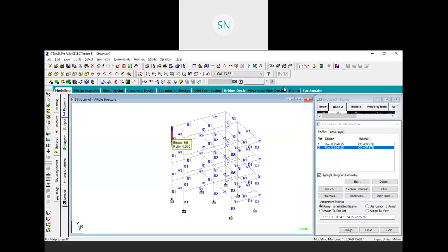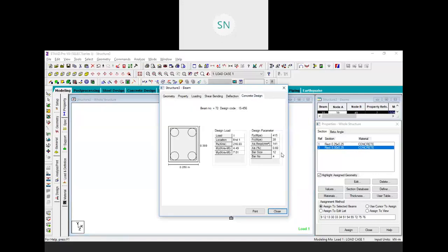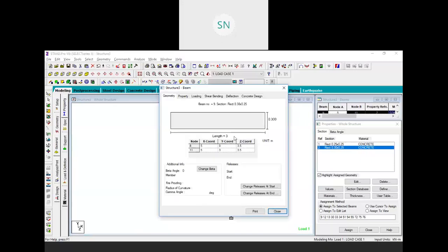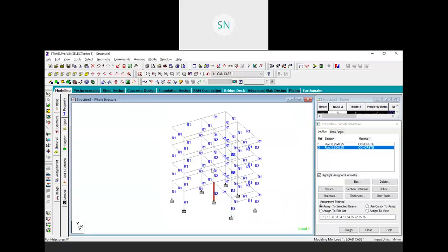But we have to focus only on ground floor columns and beams. Here, see 0.6%, and on the bottom we still have 1.2%, right? But we still have to provide 1.2% steel in this entire column up to the top, right? So this is our design and optimization.